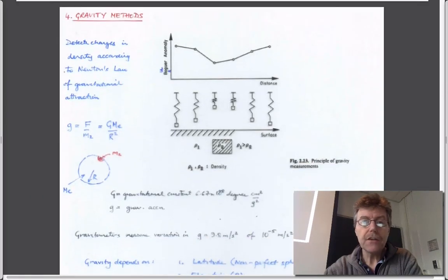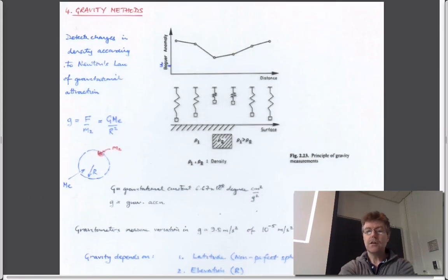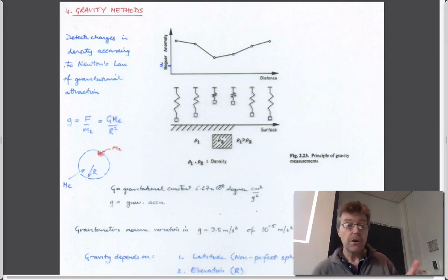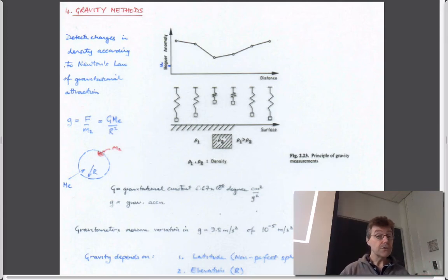Gravity methods, I think, are exotic, not used so much in environmental geophysics, primarily because you're not often looking for caves, and that's really what they pick up. And the basic idea is that you can imagine that if this room was filled with lead instead of you, and you measured the gravity next to it, because lead is much denser than the air and the earth around us, it would measure an increase in local gravitational constant, 9.81 meters per second squared, next door to it.